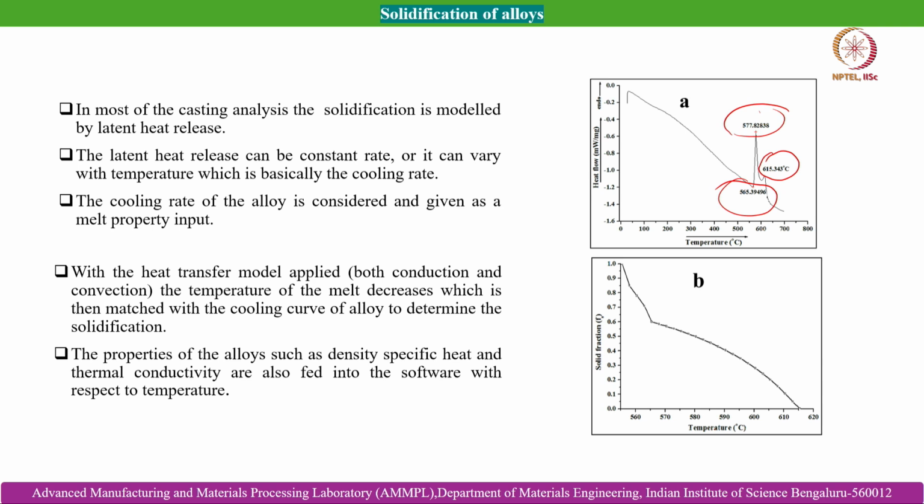Even if we do the same process in gravity, that means the Rheo gravity die casting process, these temperatures are essential to decide the process window. This is the TL liquidus temperature, this is the solidus temperature, and this is the TE, the eutectic temperature. We generally need to be in between the TL and TE. We should not go below the eutectic temperature, even if theoretically it is possible to process the semi-solid slurries between TL and TS.